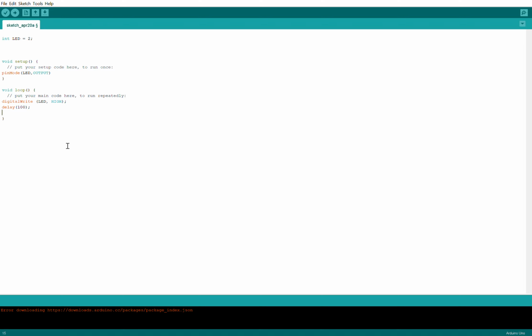From there, we want to turn it off, right? So I'm saying digitalWrite LED, and we want it to turn off. So what do we say there? We say LOW. We close.